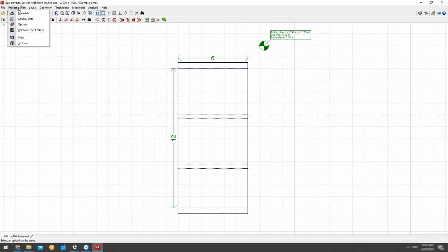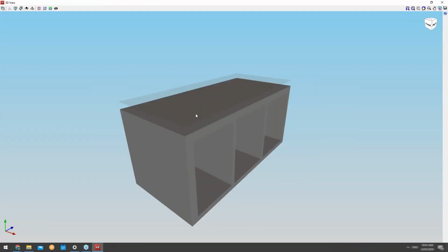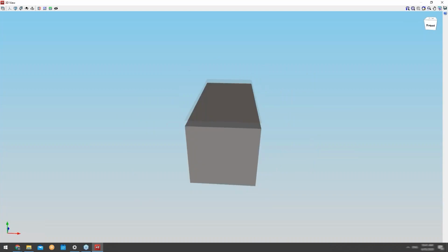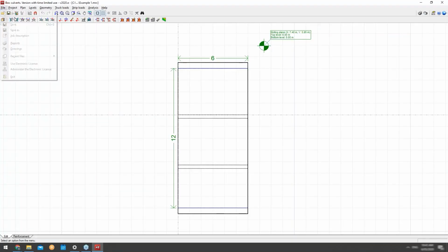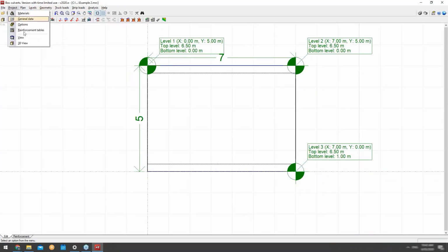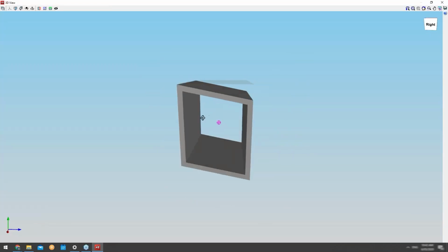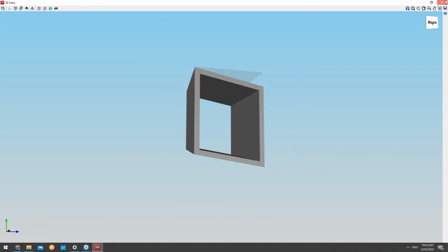So this is a simple wing wall with two lateral cuts as such. So not taking into consideration any wing walls, etc. Just a single box module. The next one is a culvert with trapezoid section, so something similar to what we've done in today's webinar. You can see here we can introduce different angles, of course, to model with the ground.